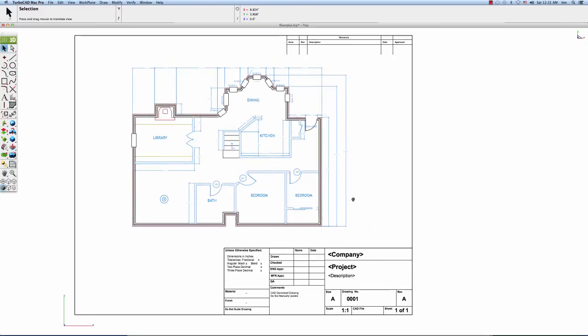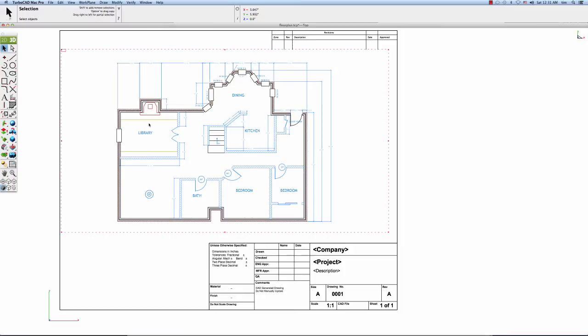Let's go ahead and show that more by, let's click inside of our draw view. And we're going to create a line. Let's make that line 100 inches long. Now I'm going to click outside the draw view and I'll make another line 1 inch long. And if we go ahead and take our gripper and pull these near each other, you can see the 1 inch line outside the draw view is measured as 100 inches within the draw view. In fact, let's go over to our scale now and let's change it so 1 inch equals 100.